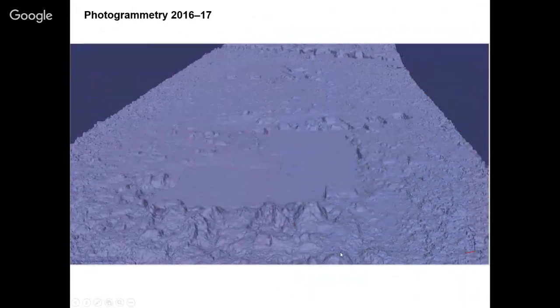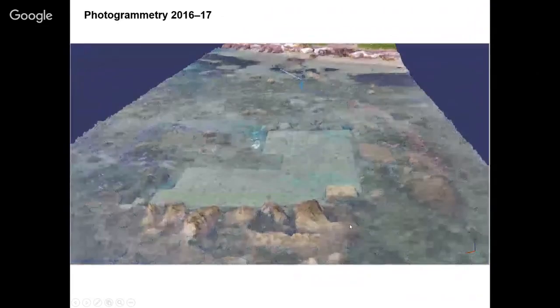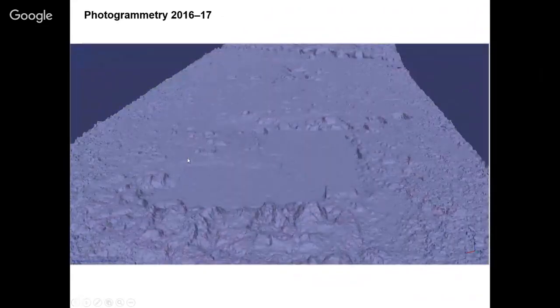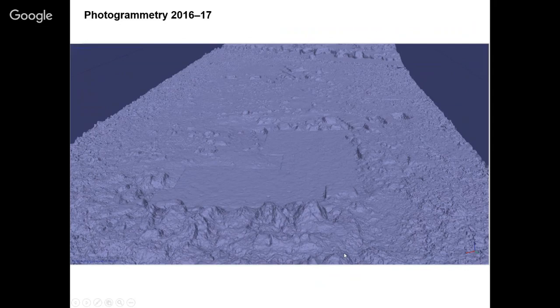So this one is done from the aerial images, and then that's the one where it's been textured. And here it's actually not a large area, so I think I have about 10 fixed points in the sea that are measured with centimeter precision, and that way it makes it possible to work out where the photos of the photogrammetry have been taken.